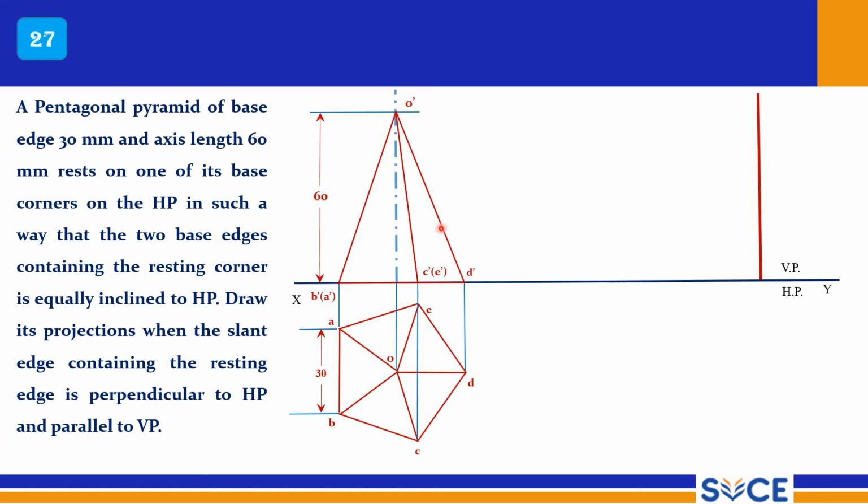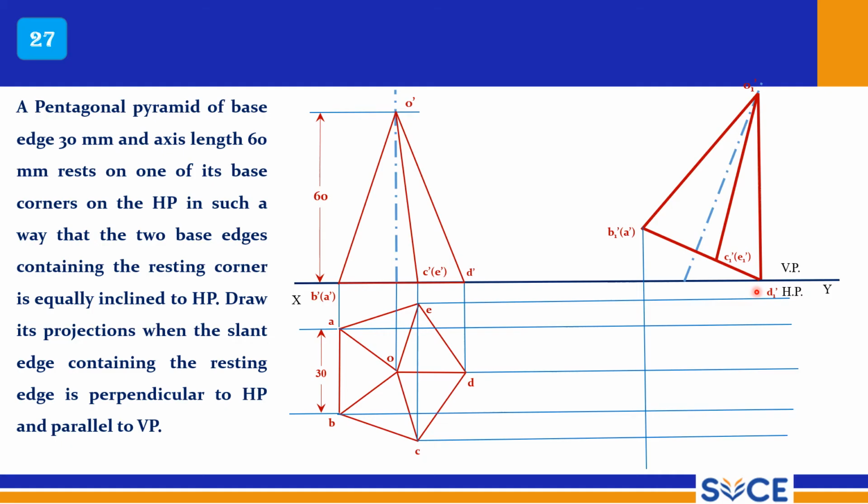Now this is the OD, right? This is the OD, so that should be drawn with a thick line and straight at 90 degrees. Now you complete this view and you reproduce this view with respect to this vertical line, right? So the corresponding top view is very simple, and you get 2 points here, right? O and D. So this is my top view.